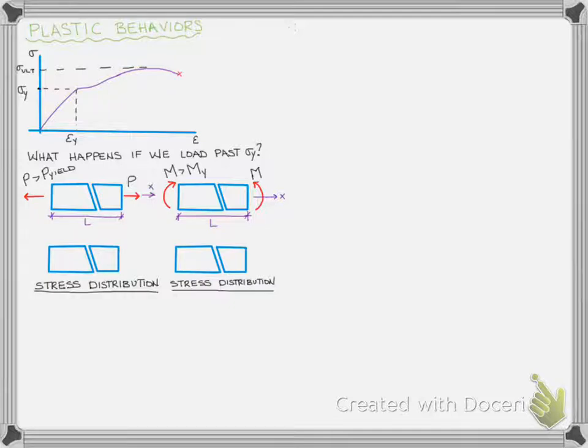And if we look at how the stress distributes, when we think about axial loading, we know that where P is applied can cause local deformations. And so if we get that local plastic deformation, if we're too close to the support and not further back in where the load has distributed out, we're going to get this parabolic distribution instead of our nice linear distribution that we're used to seeing. And we're going to say that that's just our axial stress that's now acting.